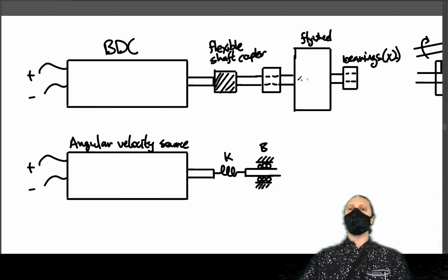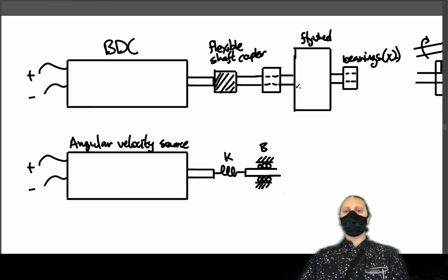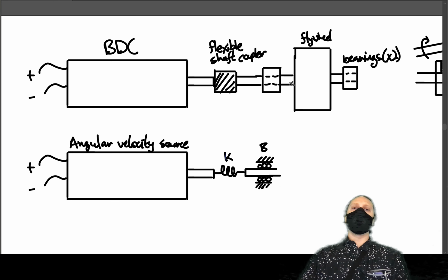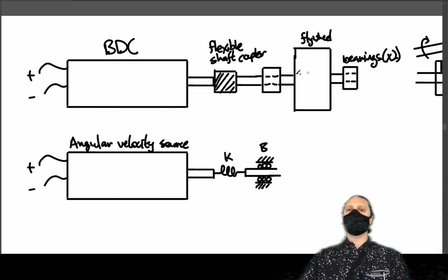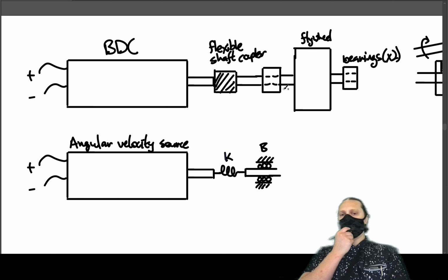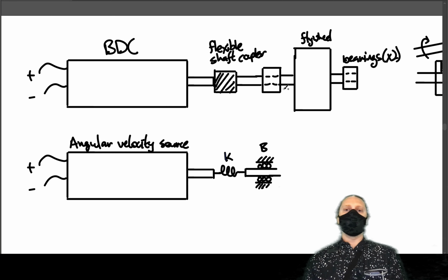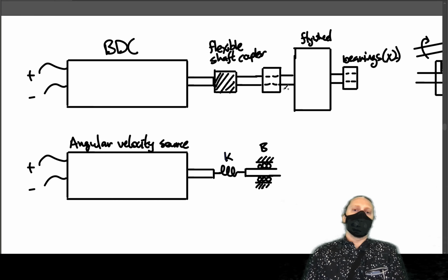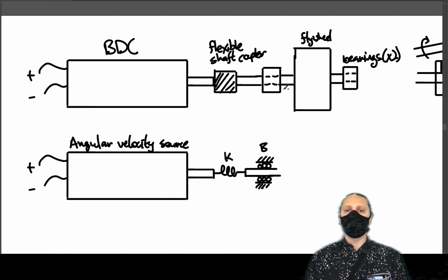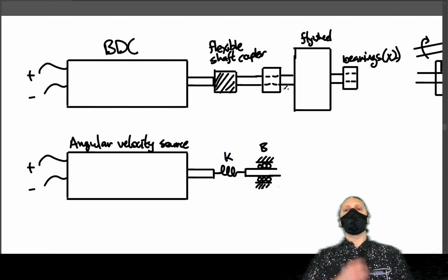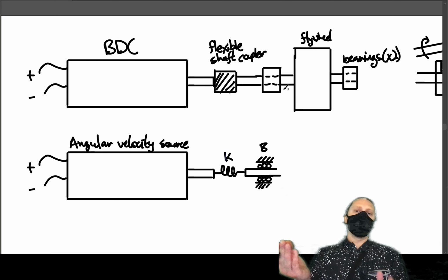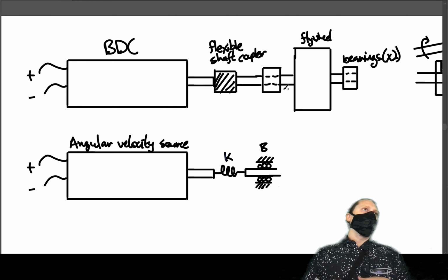Okay, so this shaft is relatively short with a flywheel on it, as far as we know. So we aren't going to have any difference in angular velocity across this flywheel shaft portion. So if they're all at the same angular velocity, all the bearing damping torque will be proportional to the same velocity, and the 2 bearings will be in parallel.